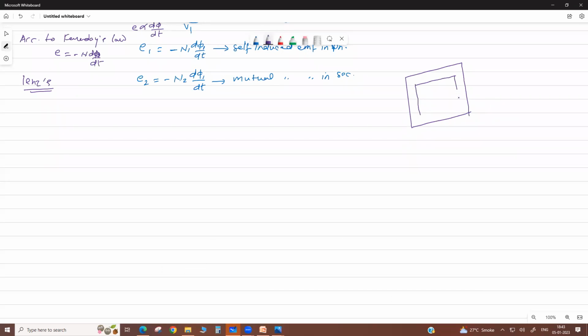It is like this when we make a core. A number of plates are put together like this, correct? Then we make this thickness of core, a laminated core. Why do we use a laminated core, my dears? To reduce the eddy current loss, core loss.